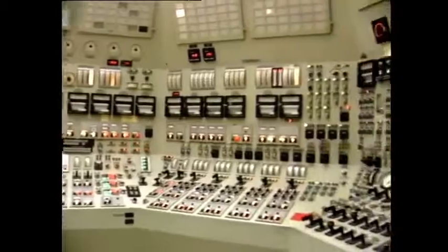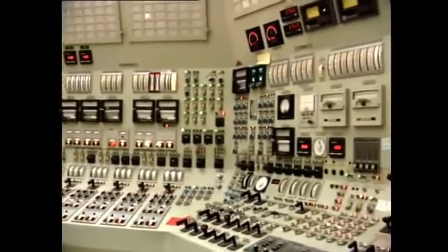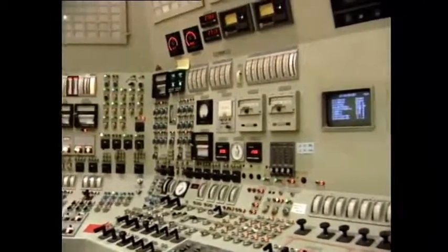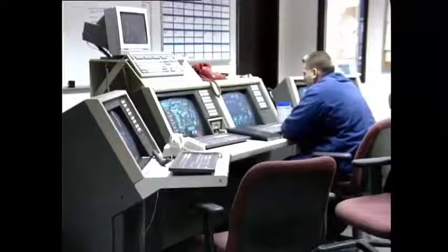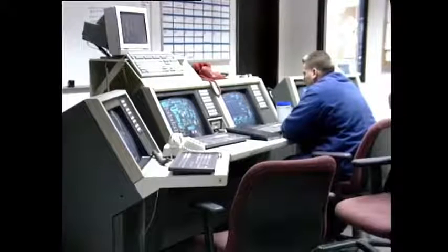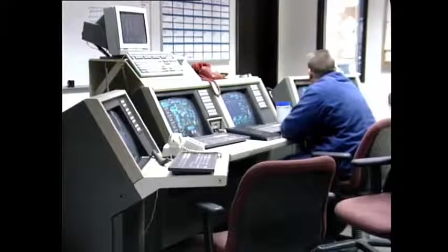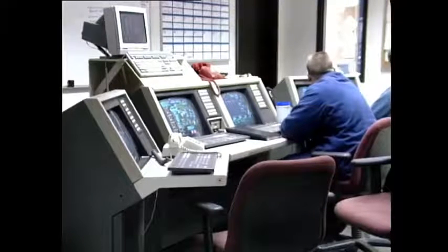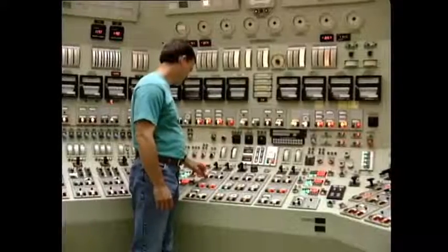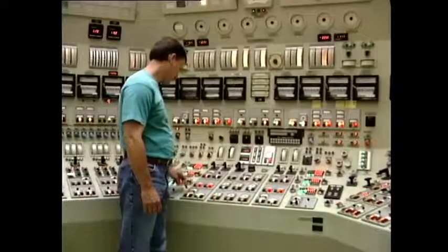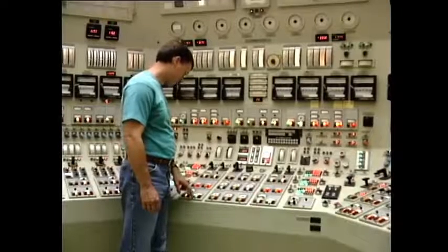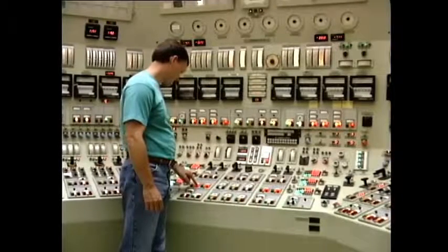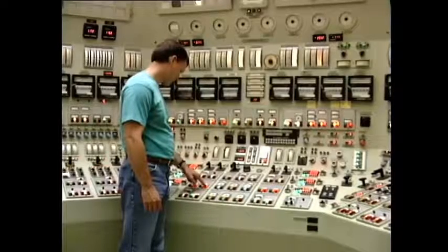We have already studied monitoring equipment, both the traditional control panel and the modern operator's console. In either case, the operator is able to stop and start equipment and make adjustments remotely, that is, from his central operating position. The operator can also manually adjust all of the major operating parameters, such as fuel input, combustion air, feed water flow, steam temperature, and so on.